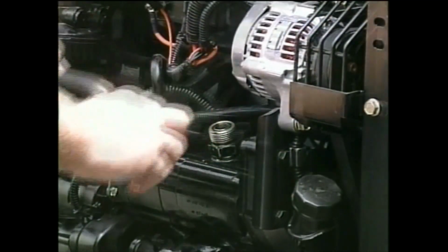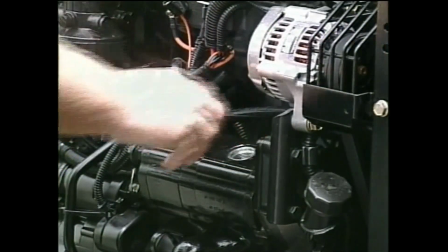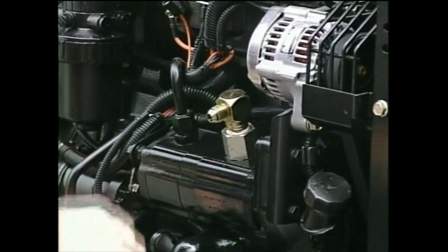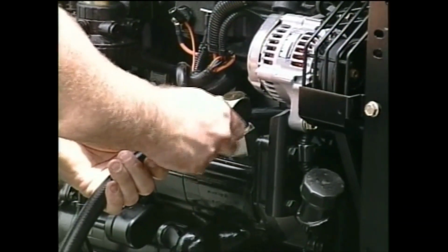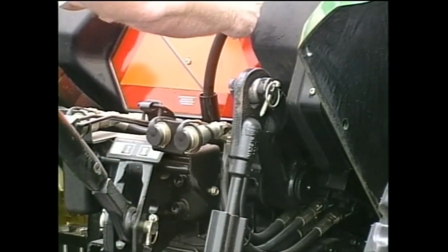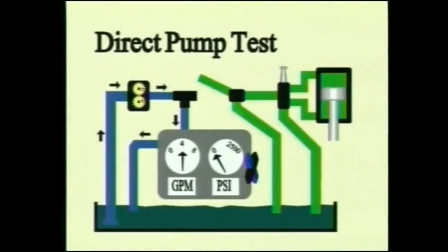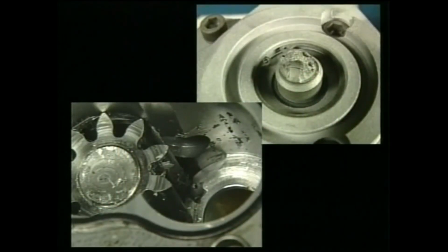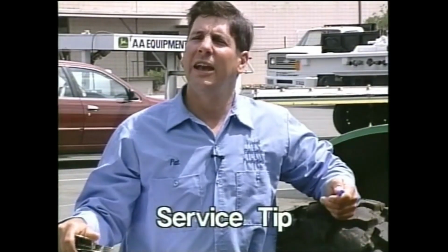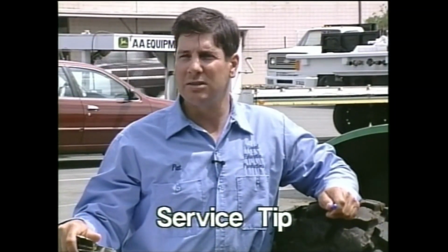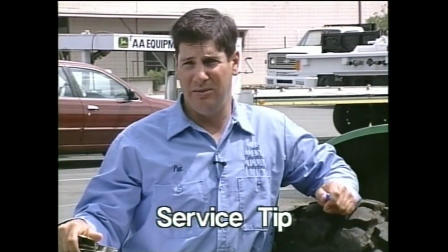Isolating the pump is done by removing the pump outlet hose or tubing from the system and coupling a pressure gauge, flow meter, and control valve to the pump outlet hose. Next, a hose is connected from the control valve to the reservoir fill hole. Remember to always open the control valve before the engine is started, because there is no relief valve in the pump circuit during the direct pump test, and the pump drive shaft or housing could break from excess pressure if the control valve is restricted. If you encounter a broken shaft or cracked pump body when servicing a machine, be sure to look for the possible cause of the excess pressure that damaged it.